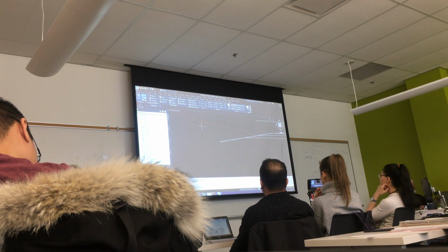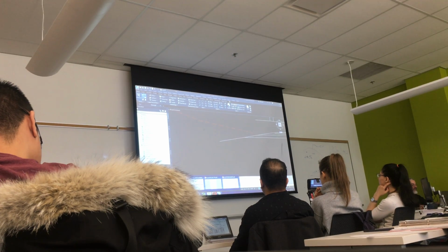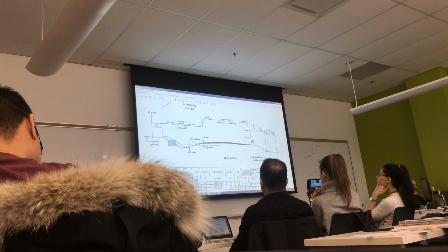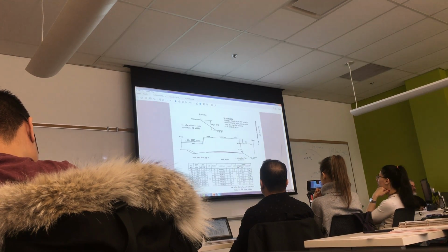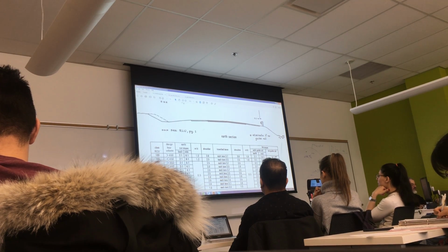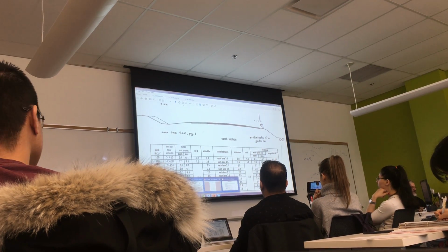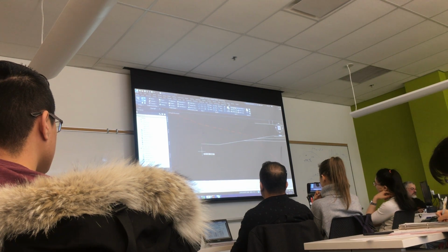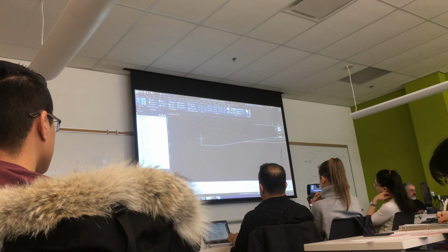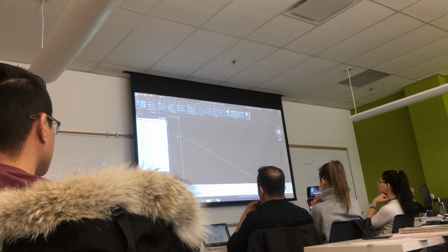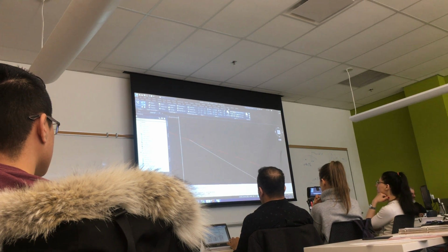And then from there, to go back to the original ground, this slope, the back slope is always 2:1, regardless of standard. Let's go look at RCU, right? RCU, the 91, it's always 2:1 to go back. So go back to the drawing. From that point, I'm going to go horizontal 2, vertical 1, close, that's the angle. And I'm going to extend until I hit the original ground. So there's my ditch. Offset 1 meter.